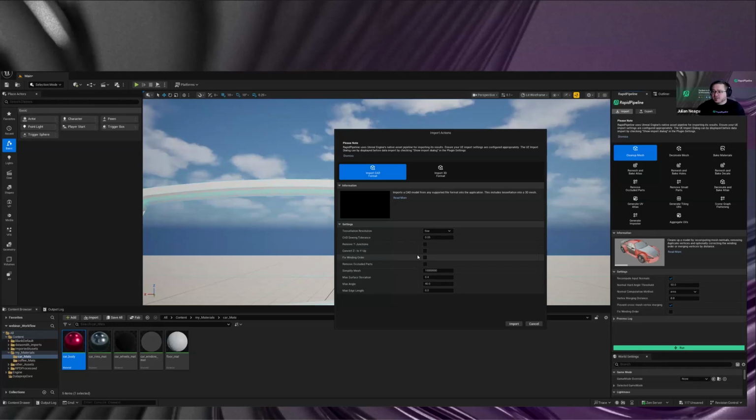Of course, with these actions, we try to be as concise and simple as possible. They have a lot of automation, a lot of expert settings on the backend, but we try to get the best defaults for you guys so you can just select the automatic function. For example, there's the winding order correction. There's also what I wanted to show here, the sewing tolerance, which is also in millimeters. Right now the default is 0.05.